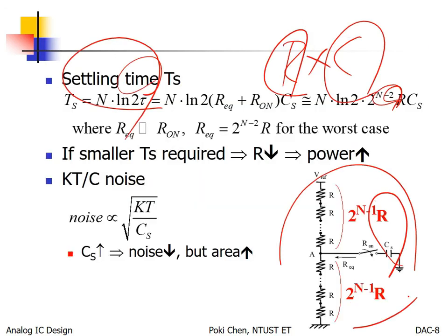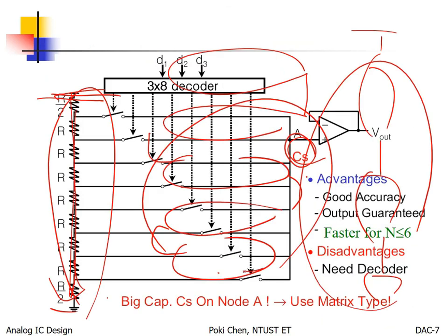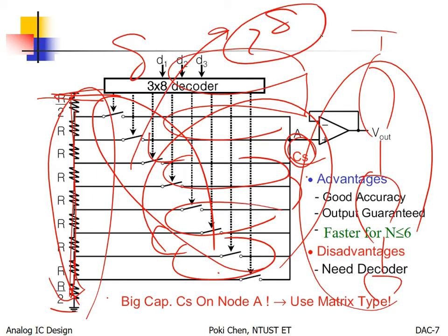If you go back to see the original one, sorry, you have 8 bits. So in total, it means what? The parasitic capacitance is reduced by how much? Oh, 16 times. The more input bits, the more you can save on the input capacitance.